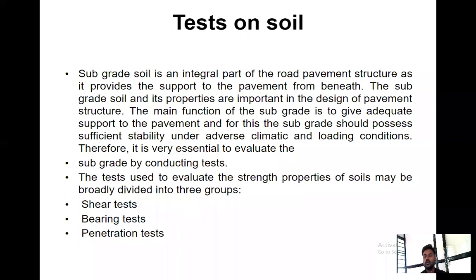The main function of the subgrade is to give adequate support to the pavement, and the subgrade should possess sufficient stability under adverse climate and loading conditions. Therefore, it is essential to evaluate the subgrade by conducting different kinds of tests.